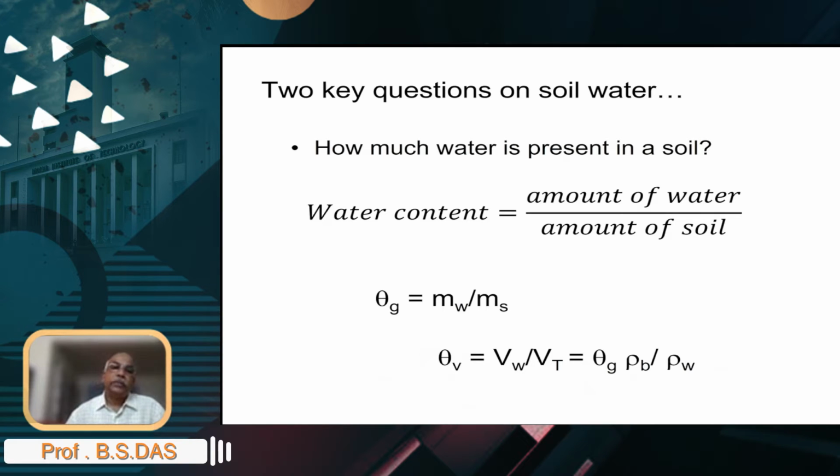So this gravimetric water content is defined in terms of the mass of the dry soil, and not in terms of the moist soil weight, because if you take moist soil weight in the denominator, then depending on how much water is present, the denominator would also change while the mass of water itself is changing.